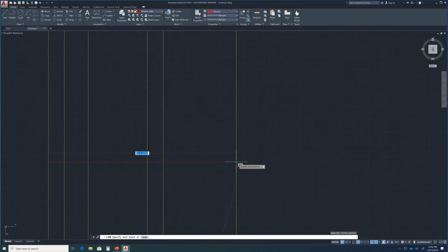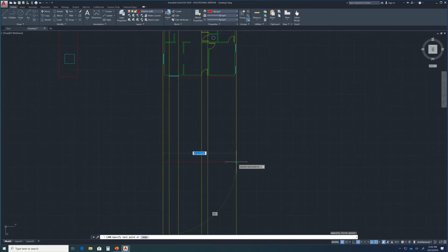And that's kind of what this little symbol does. The symbol doesn't get any larger, but if you see that symbol that's in my cursor right now, that basically indicates that we are perpendicular. Right here, it looks almost like an hourglass, and that does not represent being perpendicular. Now it does. And it'll even tell you that you're perpendicular in the little side dynamic input.